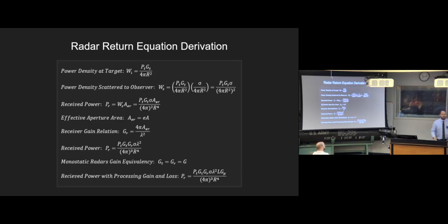In this case, let's say you had a circuit generating your signal, but it's not a high power circuit. It generates a signal that's 1 watt. Gain is basically just a multiplicative factor. It just boosts the signal up. If you've ever heard of an amplifier, that's what this is doing. It amplifies the signal. Now, in this case, that's not the gain of an amplifier. That's the gain of the transmitter, which is antenna gain.